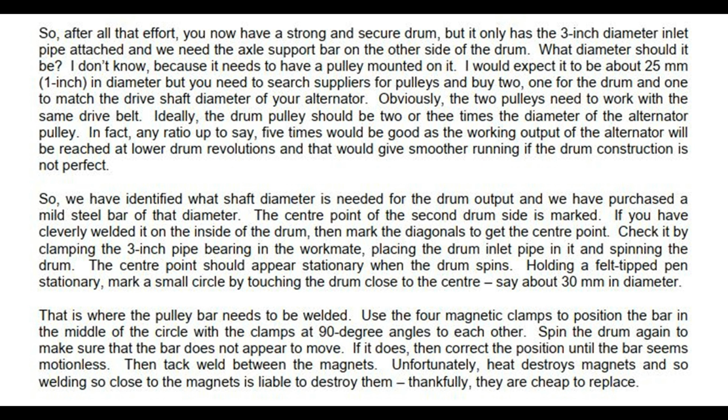Ideally, the drum pulley should be 2 or 3 times the diameter of the alternator pulley. In fact, any ratio up to say, 5 times would be good, as the working output of the alternator will be reached at lower drum revolutions and that would give smoother running if the drum construction is not perfect.